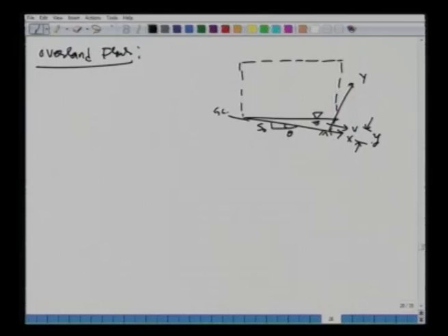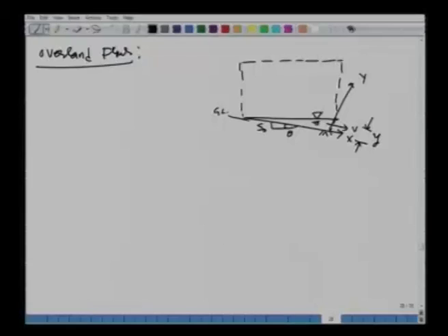and the depth of flow is, let us say, y. So, you have a sheet flow or overland flow taking place from left to right, and at the outlet the velocity is v and the depth of flow is y. That is what we want to find out in this particular case. And this dashed line which I have drawn is called the control volume, let us say, CV.